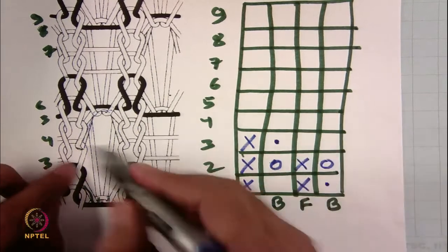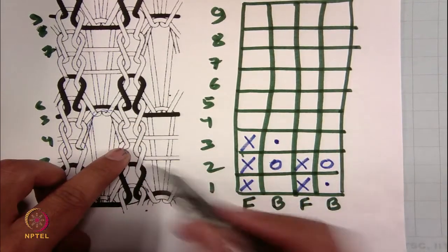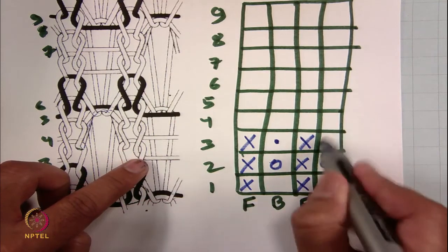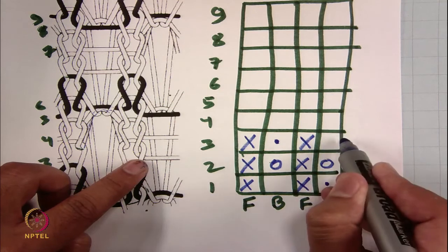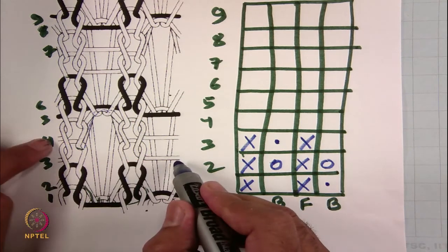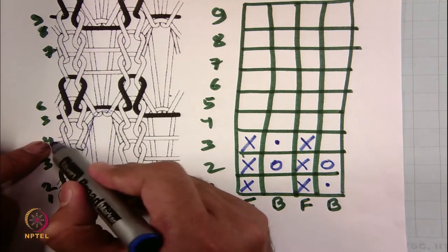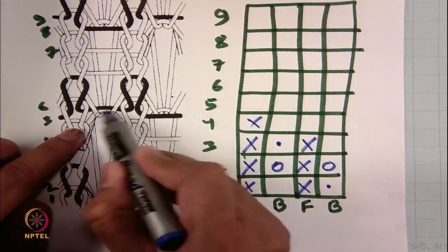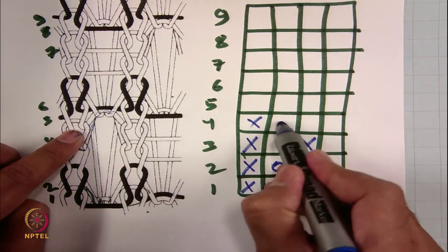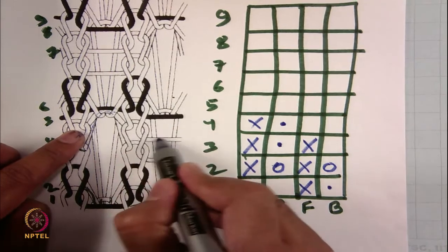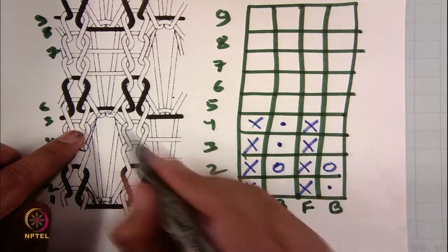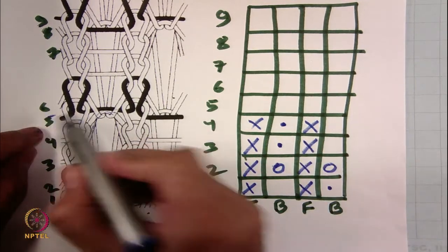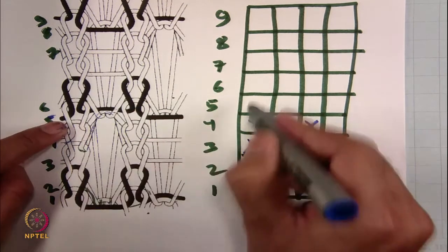So, dot, after that you are making technical front, and after that this is straight yarn. So, this is a float part, this is float because this is a straight part. If you go for the fourth course, again this is technical front, fourth course, and then you can see this is again a tuck. So, dot, then again if you see this cross, technical front, and again this is float.